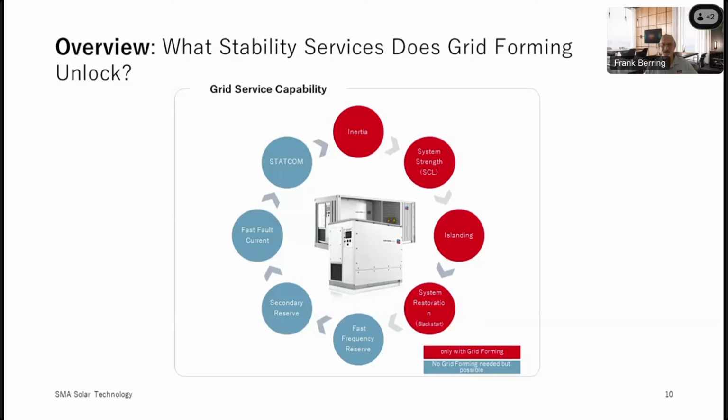You can talk about these capabilities at the inverter level or at the POI. For example, we provide inertia, as you've heard from us here today over the last hour. We tend to talk about inertia at the inverter terminals, and about how the inverter is able to produce an inertial behavior. But at the same time, what you really care about is what's happening at the POI, right? How does that entire plant behave towards the grid, and how does it provide stability to the grid? And that's a measurement at the POI.